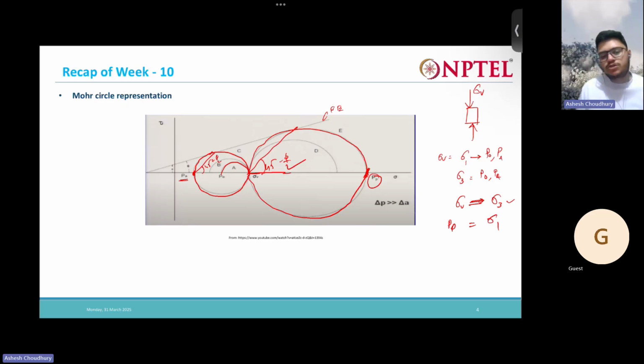Yeah, so the active pressure and the earth pressure at rest are always less than my vertical pressure. Some coefficient times the vertical pressure gives me the earth pressure. So that coefficient is always less than 1 for active pressure and for your earth pressure at rest. And for passive pressure, the earth pressure coefficient, which when multiplied with the vertical stress gives my earth pressure, is always greater than 1.